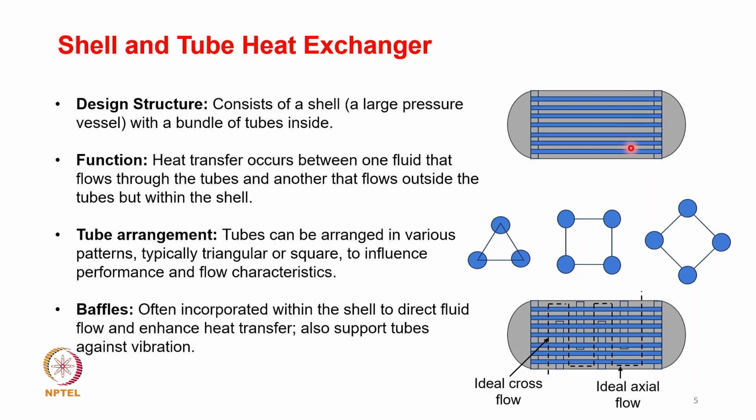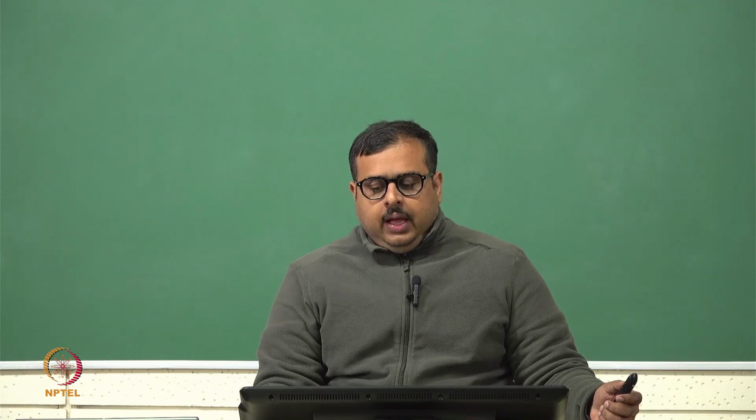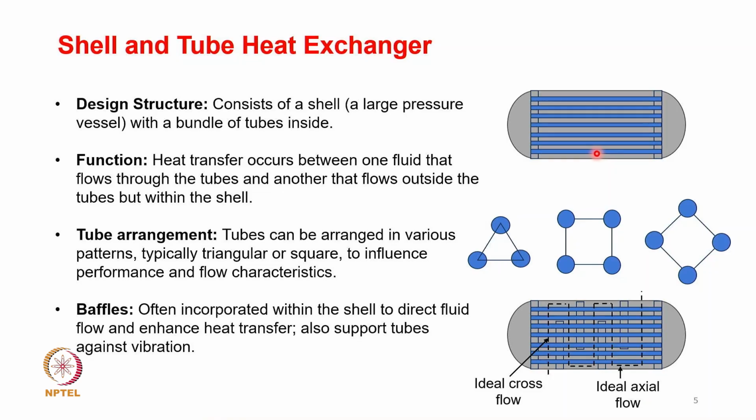and that would eventually result in heat transfer. And on the tube arrangements, as I previously told, the tubes are arranged in stacks. There are various ways in which you could arrange these tubes, and that is typically known as tube pitch. Tubes are arranged in certain bundles, and you can't stack the tubes together without spacing.